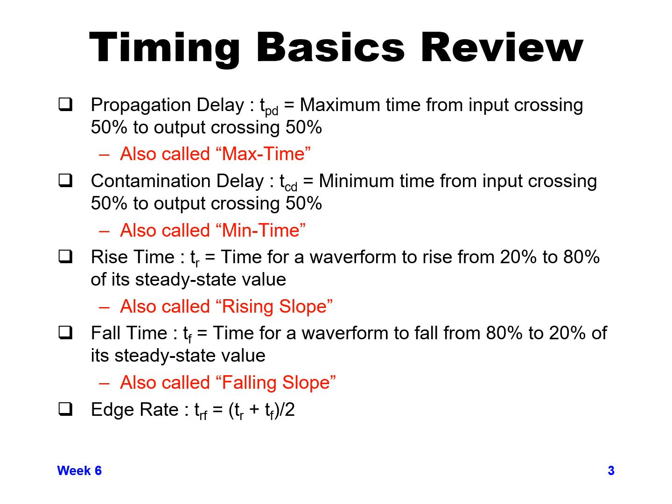Sometimes you will have the average of the rising slope and the falling slope, or rise time and fall time. If you sum the two together and divide by 2, that can be your average slope, which could also be called your edge rate.